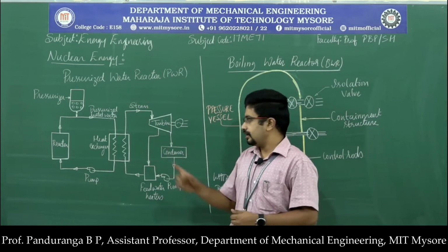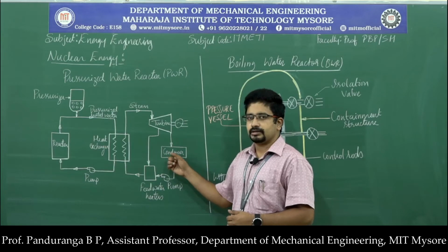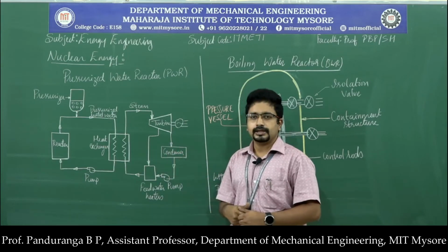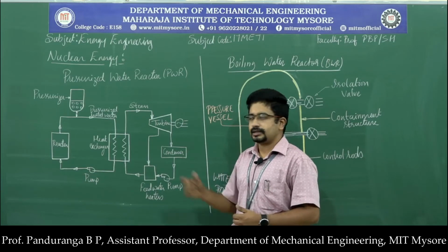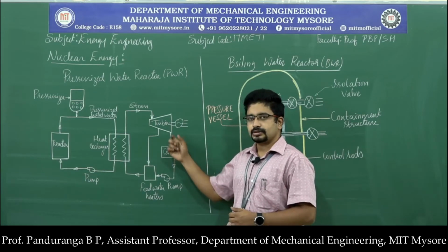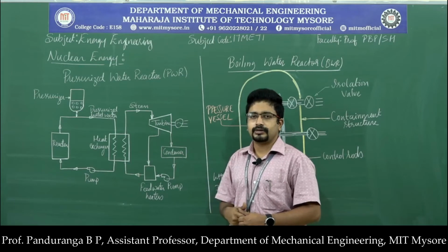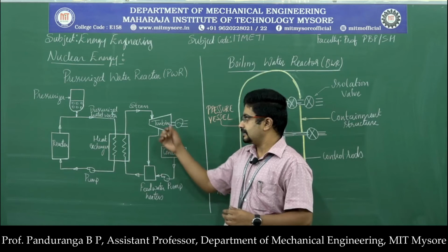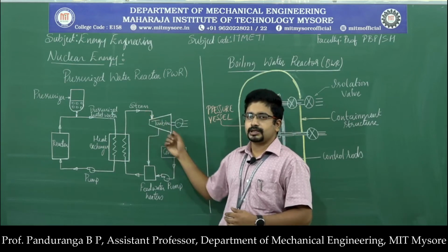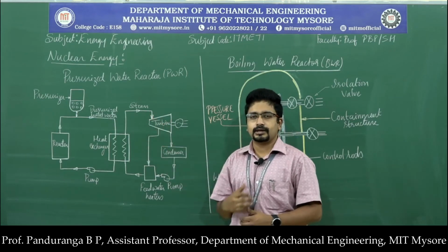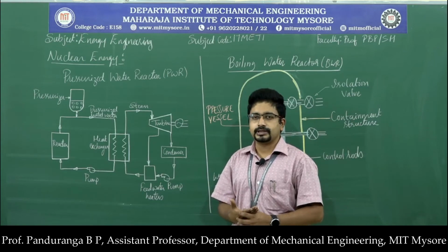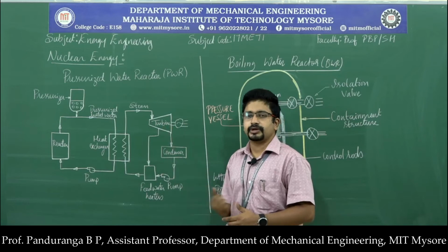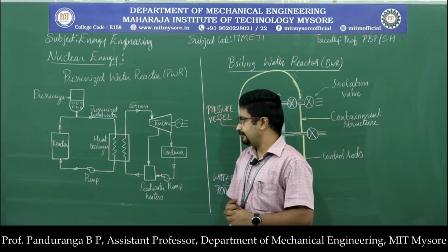Condensing the steam coming out of the turbine also reduces the pressure at the end of the turbine. Generally the turbines are reaction turbines or impulse reaction turbines. In this case, the pressure difference across the turbine is the amount of energy that can be extracted, so that increases the amount of energy extracted in the turbine.